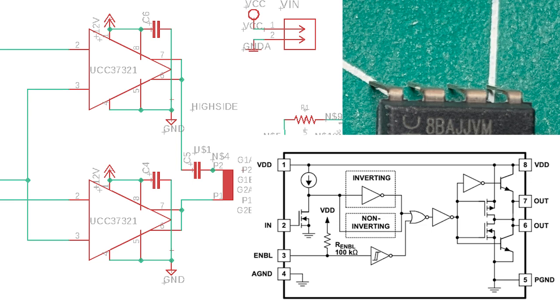These chips are extremely temperamental, and if I looked at them wrong, they would just blow up. I eventually figured out that I needed to put some sort of load on the outputs, such as the MOSFETs or a couple of load resistors, because without it they would just oscillate crazily fast and blow up.